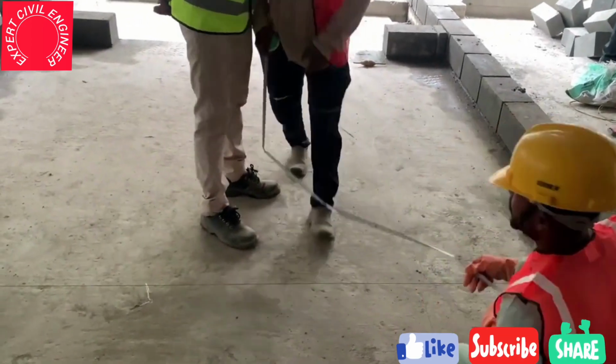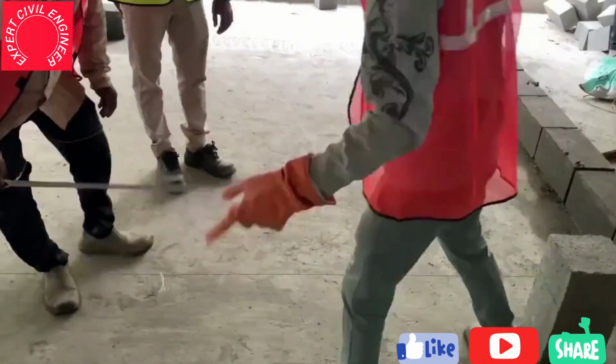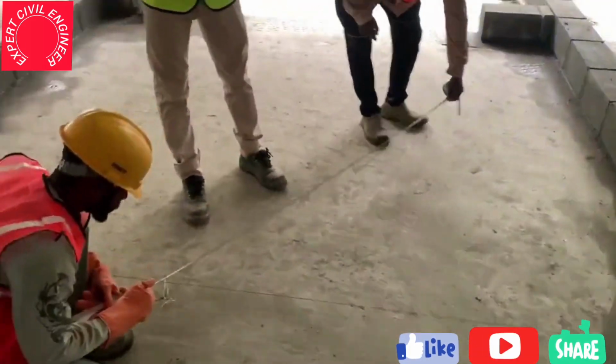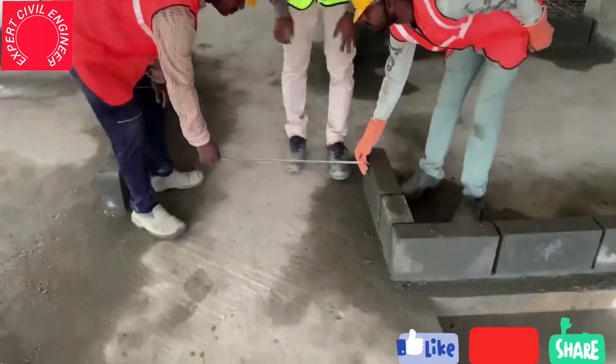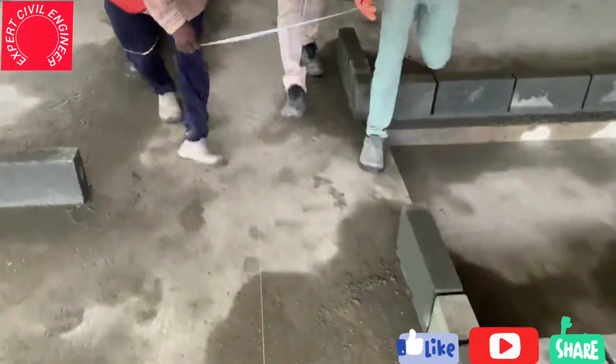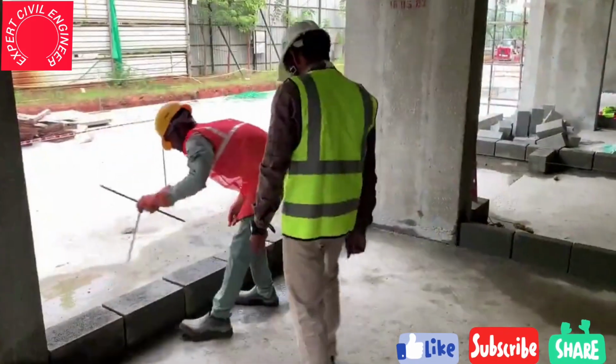After completing the first course of blockwork, the installations to be cross-checked before packing to ensure that the marker course has been executed accurately as per drawing. This inspection involves checking the line, level, alignment, plumb, right angle, room dimensions, mortar thickness, etc. of the marker course to ensure they meet the specified standards.